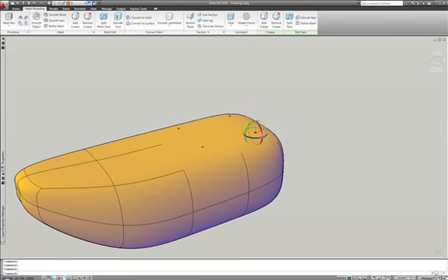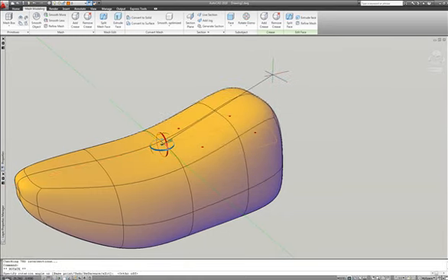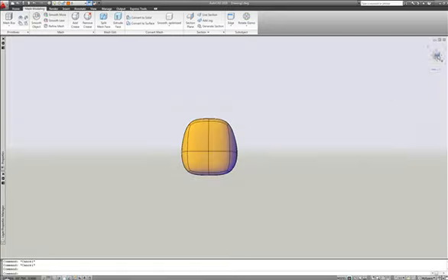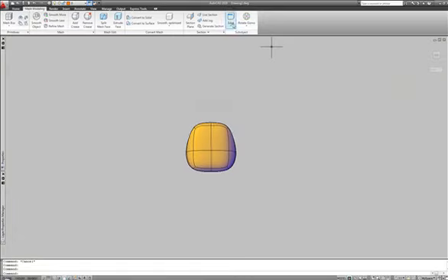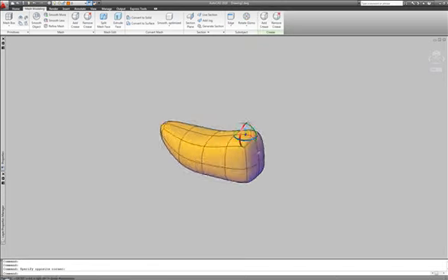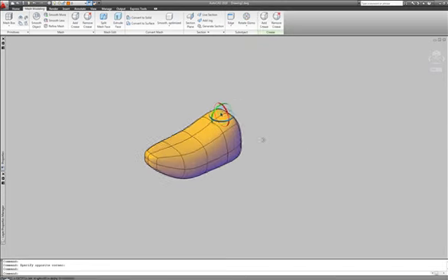The user can keep manipulating the geometry, like in this rotation, where there is an instant feedback that will allow a better understanding of the whole design intent. If there's a need to select many sub-entities at the same time, the view cube can help by quickly moving into an appropriate parallel view for a window selection.